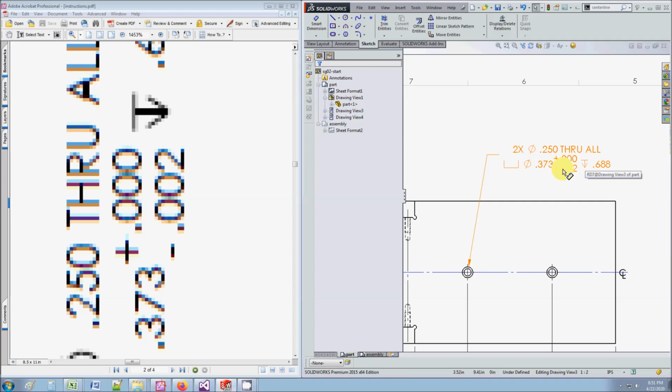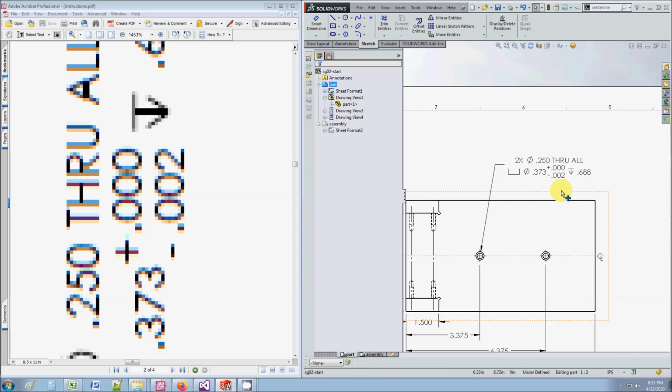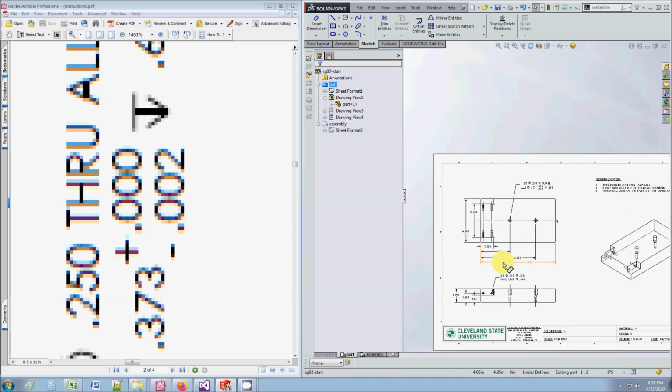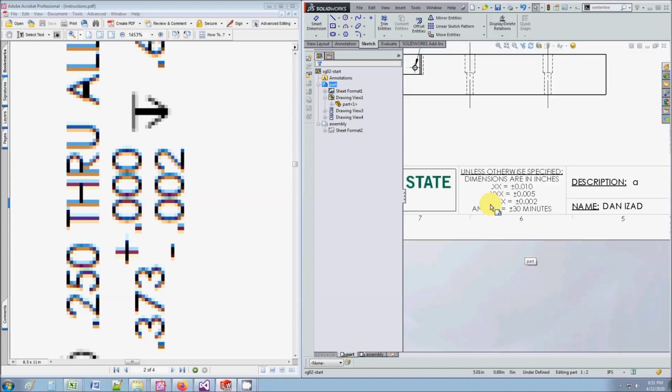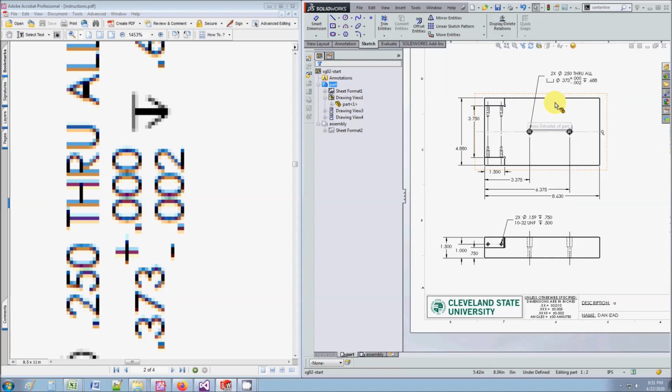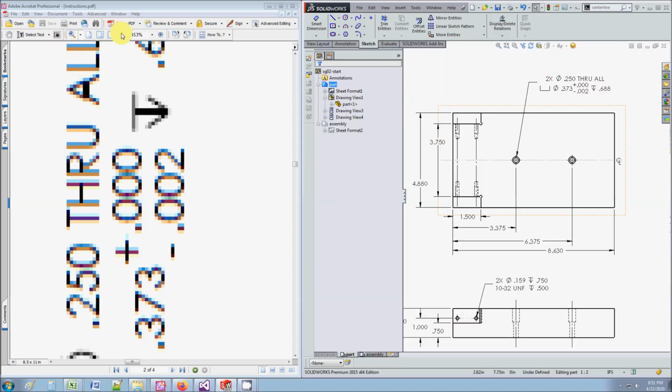The reason this is such a tight tolerance is because it's using a press fit. Interference fits are very delicate, and you do need that to be very tight. So this is to bypass the block tolerance that you see here, because this is a much more specialized tolerance.